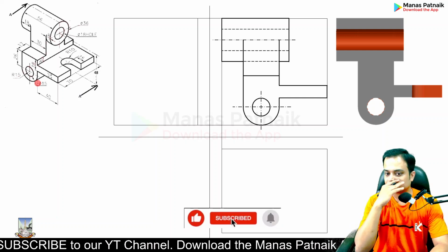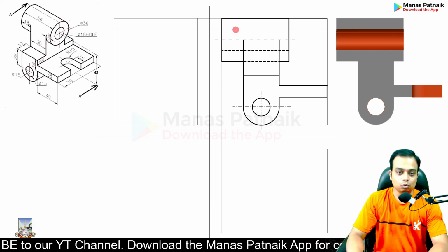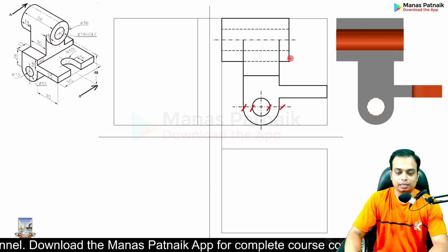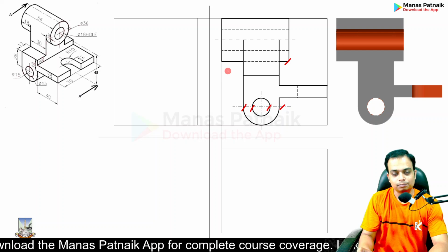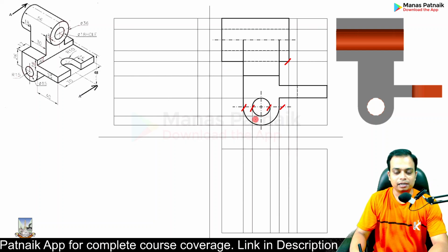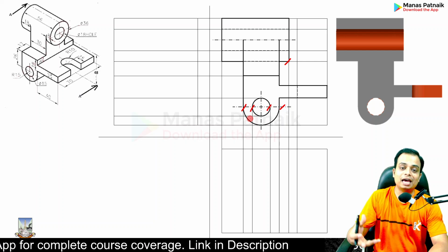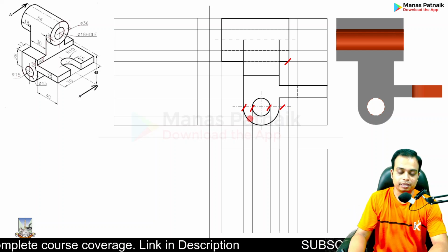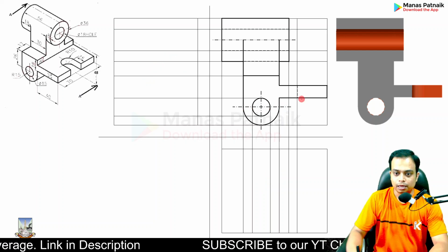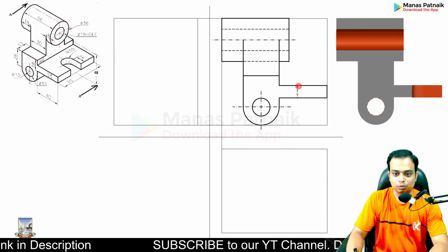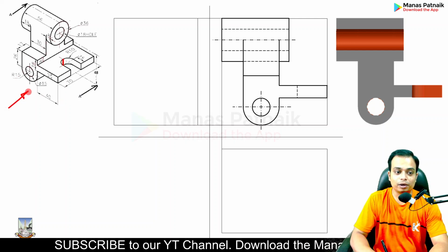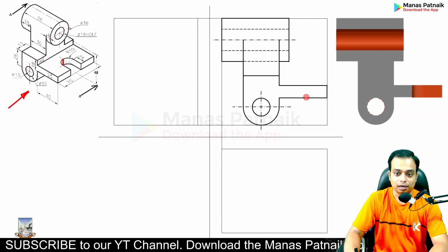So please don't mind. Now, what you are going to do is, these are the important points. And through them, you can draw lines, like this and this, both horizontally and vertically. These are the projectors which will act as guidelines. They're going to help us create the top view as well as the right hand side view, both. There is one more thing which I would like to show you. This edge, again, can't be seen directly from over here. It is hidden, therefore a dashed line.